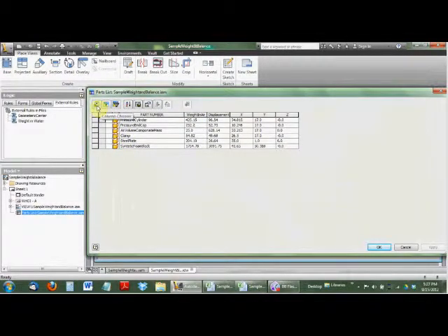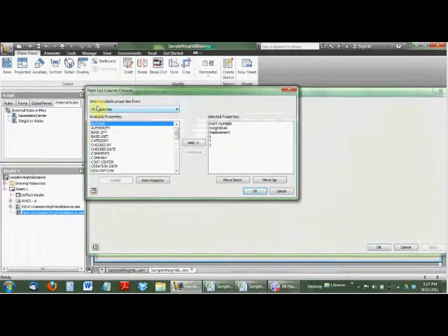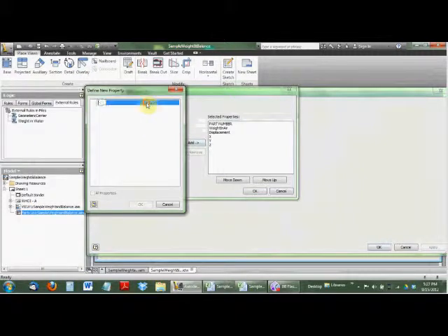You make your parts list by using a column chooser, and I chose part number, weight and air, displacement, X, Y, and Z. Obviously you can change this around by adding and subtracting from one place to the other. The way you get custom iProperties though is you have to go to new property, click here to add the new property, then you type in the variable name.